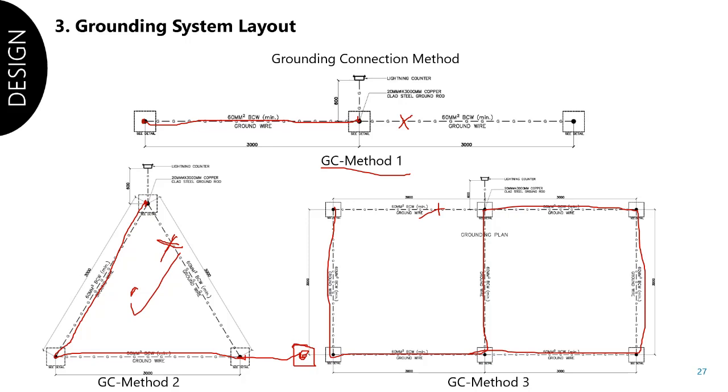Okay, and also by the way, the first part I'm saying is always our test pit, for our test. So why is it a test pit? This is a common problem neglected by a contractor or other contractors, that the design for the lightning protection must have a ground test. So what's the reason then? After your turnover, the owner or the building engineers will be maintaining the facilities, so you need to isolate this from the air terminals.